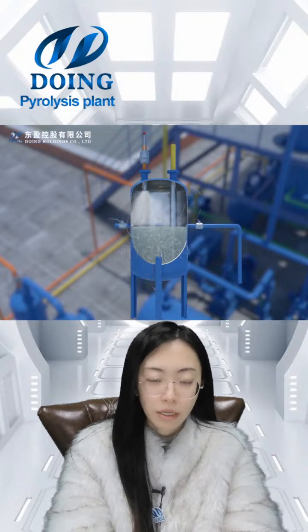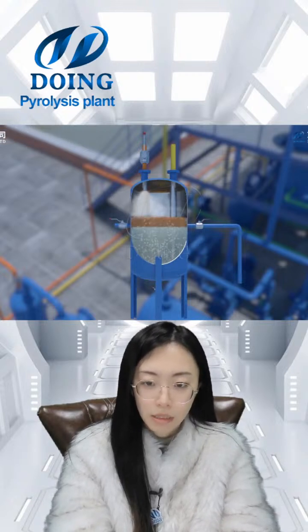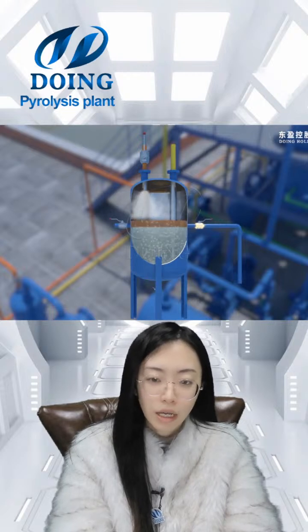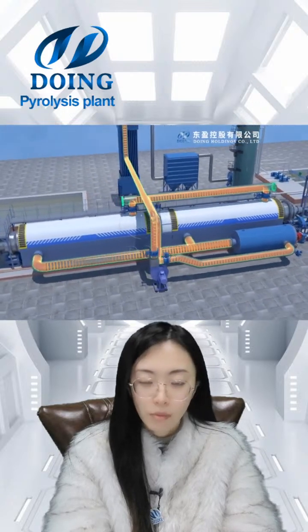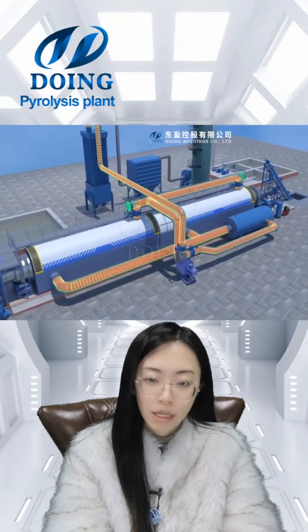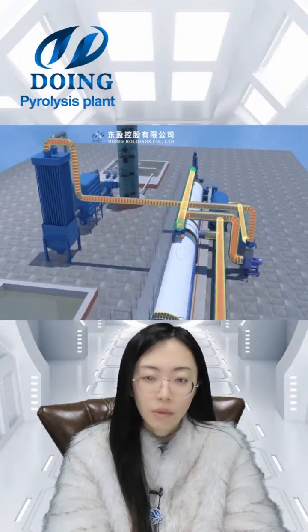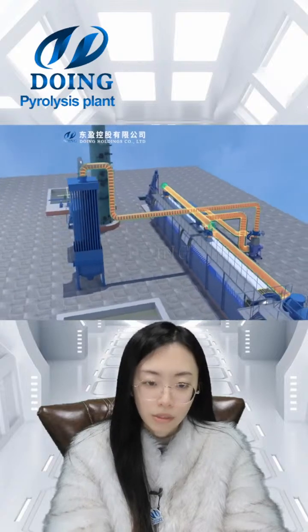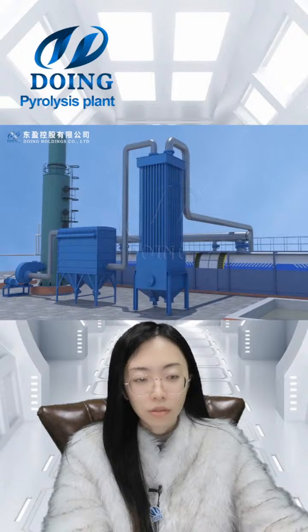All these waste things can be 100% recycled, like waste tire or waste rubber. As an example, from waste tire we can get 40 to 45% fuel oil, 35% carbon black, 15% steel wire, and 10% syngas, which we can recycle and reuse. And we have 3 kinds of technique to recycle.